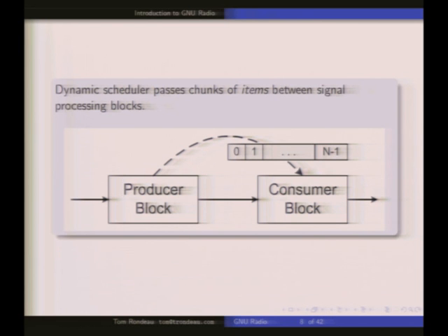Or it's the n that we let grow for as large as possible, because anytime you do a memory transfer, you're incurring overhead in your processing. And so to minimize that, you want to do as big a chunk as possible to move across there, and then process that internally in the block. So this is really why that n, that large n, is why we don't allow feedback in the loop.